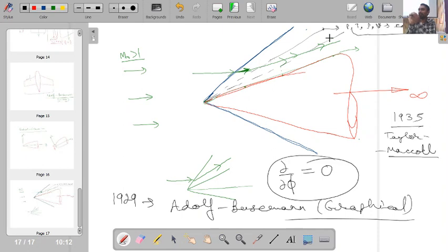Okay, so say if you have a light source, then you will have a spectrum of rays. So one ray is going, and if you rotate this ray and make a conical envelope for that particular value of phi, you will find that along that complete envelope your properties are constant.